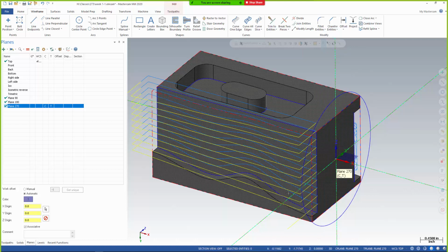You can change the biases in the post-processor to affect one bias over another. In other words, a C-axis rotation positive over negative, let's say. This is going to become more apparent when we actually look at the machine simulation when we do 5-axis work, as to which direction that 5-axis is actually going. So you can get the wrong solution.